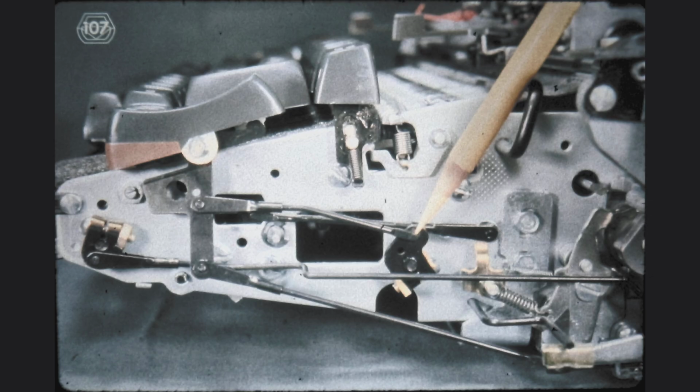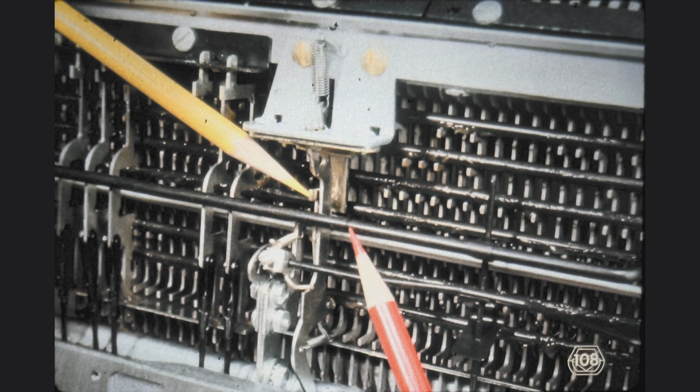Finally, we must adjust the angular position of the lockout bail, and for that, we start by loosening the clamp on the keyboard lockout bail. The lockout bail, at the red pencil, should be positioned so that it rests exactly under the lug on the cycle clutch latch pawl, at the yellow pencil, when the on-off switch is in the off position. This feature enables us to block the inadvertent triggering of the cycle clutch engagement when the machine is turned off.